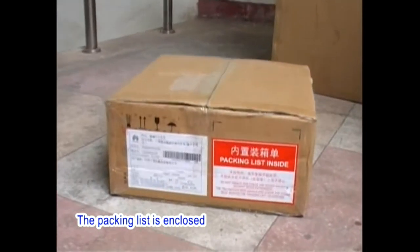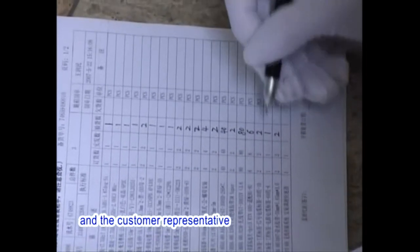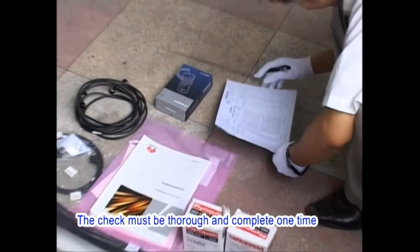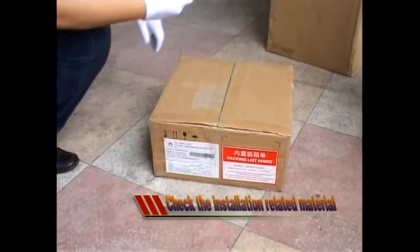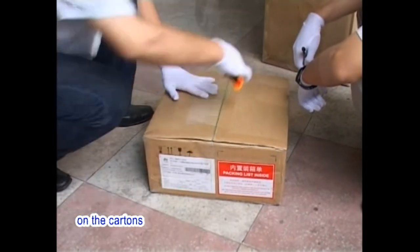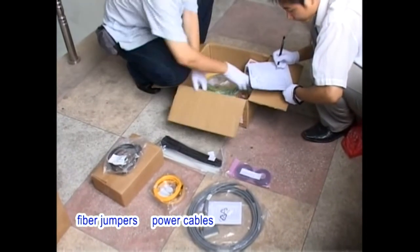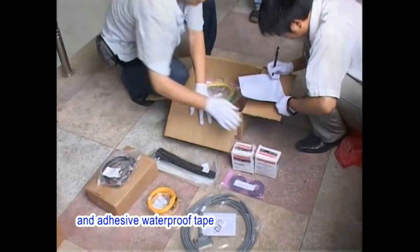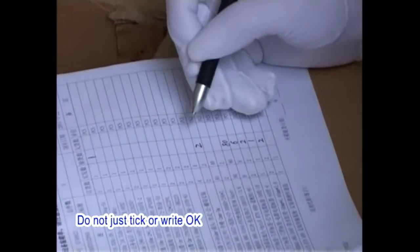The packing list is enclosed in the packing box marked with a red label. The engineering supervisor and the customer representative should check the quantity of goods, item by item, according to the packing list. The check must be thorough and complete one time and must be finished before the installation. Check the installation-related material. Use a snap-off knife to cut the adhesive tape on the cartons. According to the packing list, check the quantity of alarm cables, fiber jumpers, power cables, grounding cables, cable ties, and adhesive waterproof tape. Fill the actual quantity of each item in the packing list. Do not just tick or write OK.